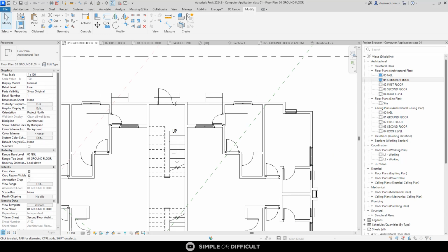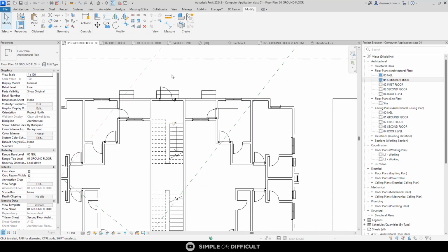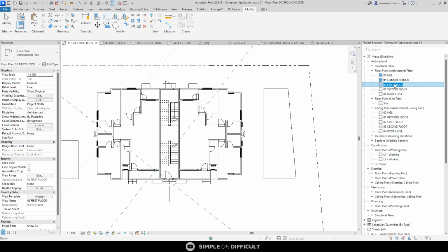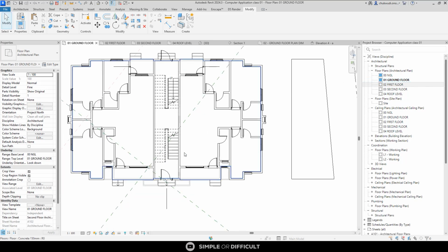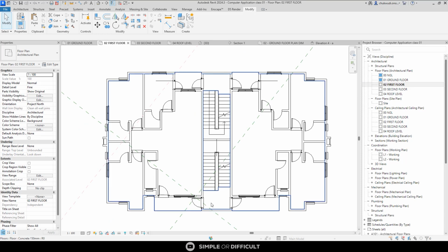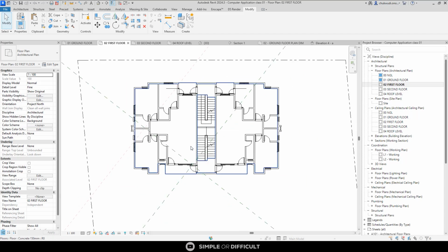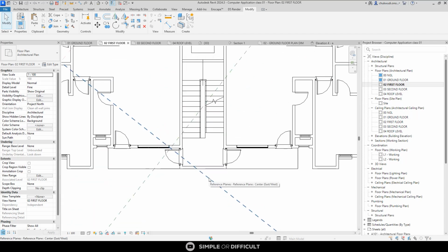The next thing I want us to add now: when you come up here, you will see that down here we have a door, but up here we're supposed to have a curtain wall that goes from this level to the upper level. So now I'm going to show you how to edit and create your own curtain wall into place. When we finish adding that, we're going to add handrails where we need them in this Revit project file. All right, so let's go ahead and add the curtain wall first.